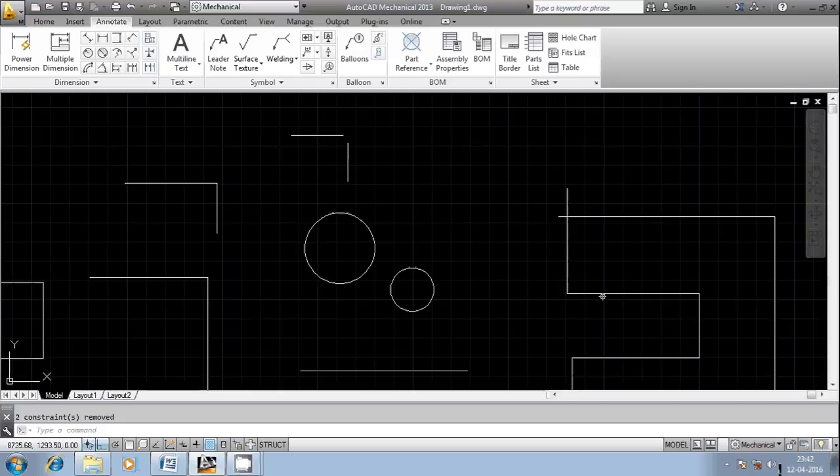This is how the fillet command can be used, using shift and then the second object. First select the first object, and then while selecting the second object, use the shift button. That's how you can create the sharp corner or the vertex. So that's how a round corner and a sharp corner can be created. Most of the interviewers are going to ask questions particularly on this. Be careful regarding this.